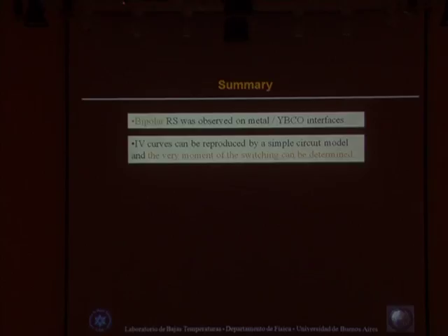So I arrive at the summary. Well, I have shown you the particular properties of switching in YBCO with the IV curves, and using a simple circuit model, we can say that we know when the very moment of the resistive switching happens.